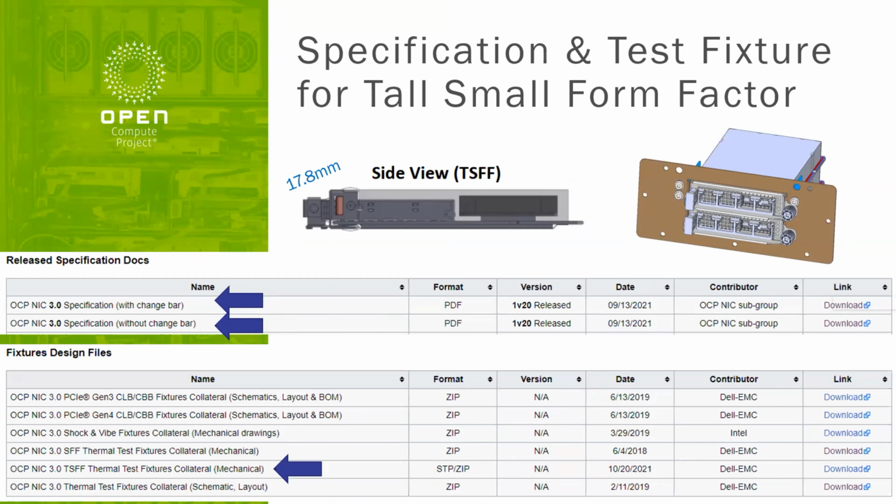That additional height allows a couple of things. It allows for taller ASIC heatsink. It allows for QSFP-DD with add-on heatsink. It also allows for OSFP HGX to be supported on the NIC cases. And as we know, on the ARG front, OSFP does have a lead. And for non-NIC use cases, this form factor also supports things like mini SAS HD.